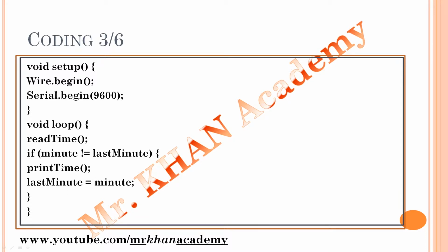After that, void loop. First we'll read the time. These are again functions. We will see what kind of commands are there afterwards. For simplification, I'm defining here the function readTime. In an if condition we'll check whether the minute from the read time is not equal to the last minute. If it's not equal, then and only then we'll print the time, and in the last minute the current minute will be stored, otherwise nothing will happen. Here we are using two functions, readTime and printTime, that we'll see in detail afterward.